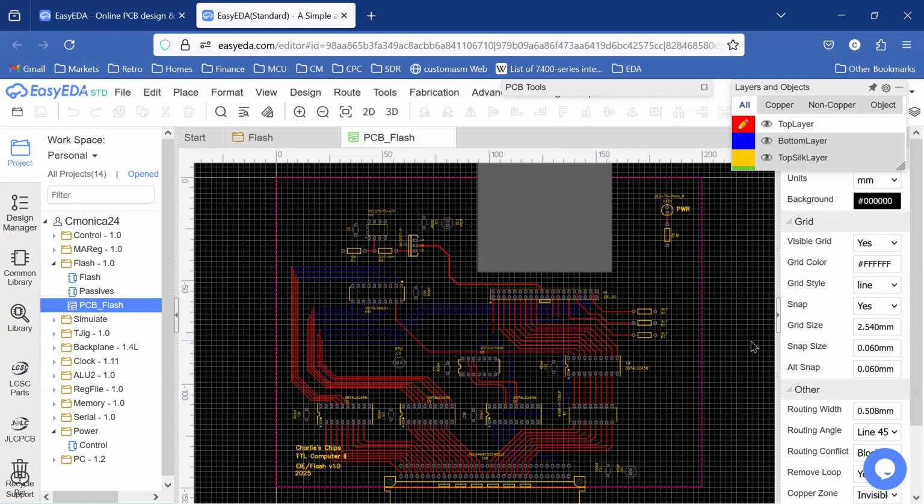And this is it. And this is using the standard dimensions for all of our expansion cards. It's 200 by 150 millimeters. We see the card edge connector here. We have all of our buffer driver interface chips here. This is the 33 ohm resistor network. Here's our buffer driver chip for our data bus. Here is our comparator to do the address decoding.